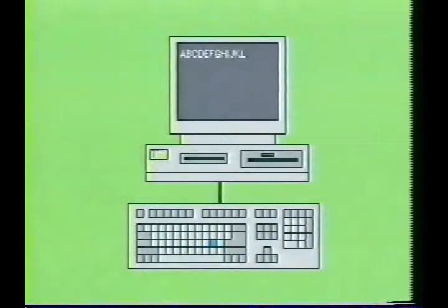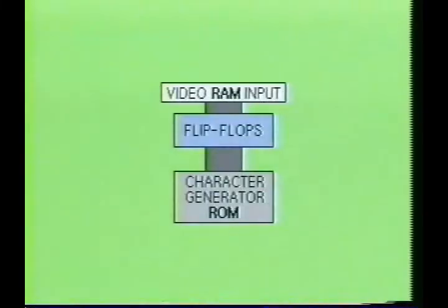As the keys on the keyboard were pressed, the characters were converted into a 7-bit format and stored in the video RAM in the sequence in which they were typed. Meanwhile, the display monitor would scan the screen with 192 electron beam scan lines at a rate of approximately 60 times a second. On each line there would be 256 dots of energy, or pixels of light. Each bit or dot could be turned on or off according to the data being inputted.